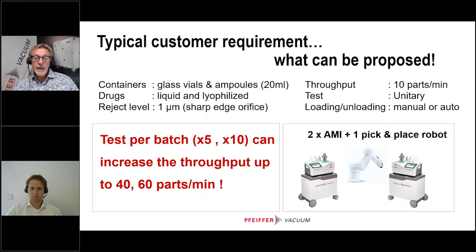But it can really make sense to size the batch in respect to the quality of your production. If you have one leaky part in 1 billion, you can test per batch, and this could be a great benefit if the throughput is a concern for you.